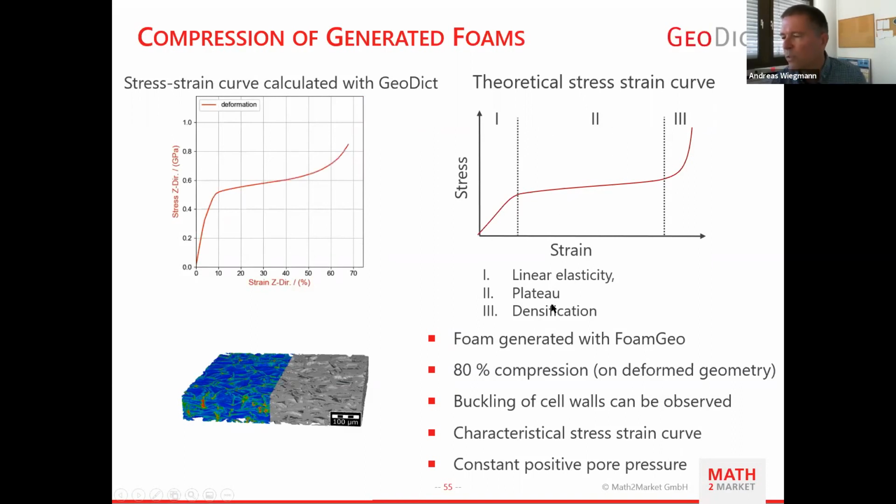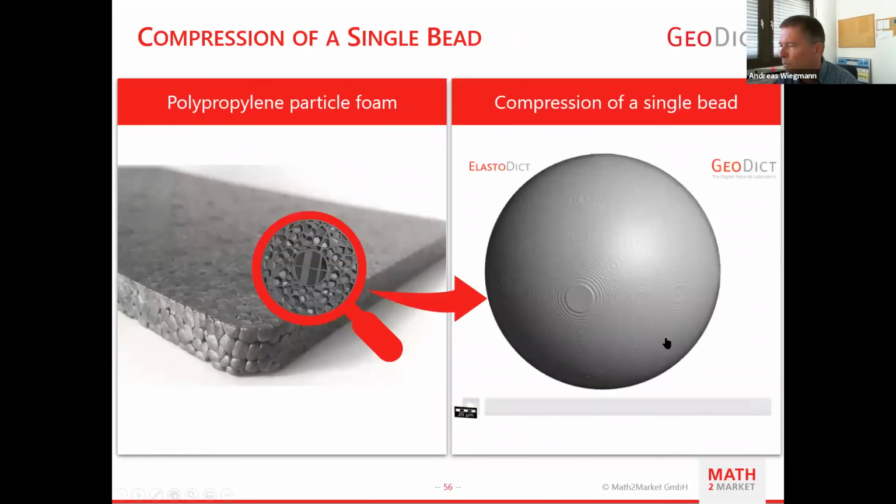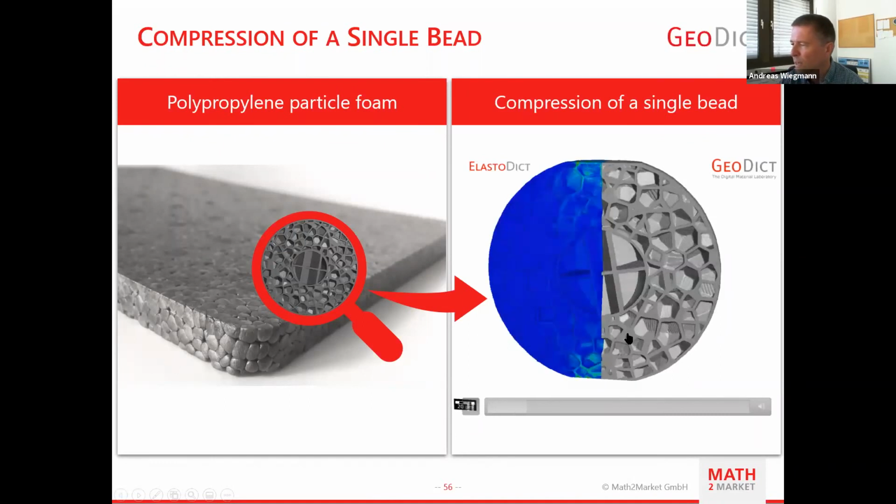To my knowledge, we're the only supplier that can do this kind of very large deformation. We're squeezing out 80% of the volume there without the software crashing. We do need to do some remeshing, but it's done automatically; you revoxelize the individual steps. We have some partners that tell us we're the only ones that can go this far with compressional foams. There's a little bit more of foam compression right here, for example.